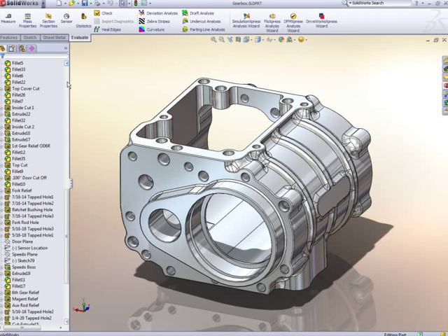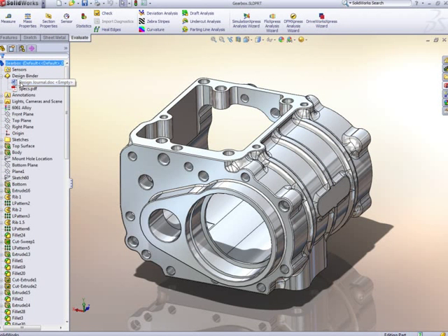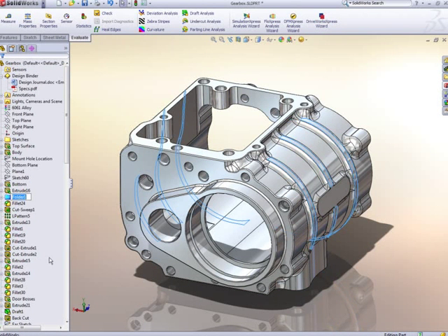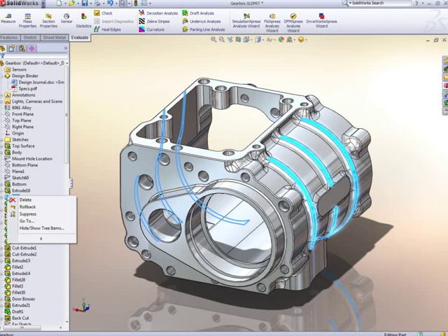Finally, let's see how information is organized in the Feature Manager. Design specs or other documents can be contained within the SOLIDWORKS file, so all relevant information is stored together. Features can be grouped into folders to make the tree easier to read, and then may be suppressed as a group as a fast way of making configurations of parts and assemblies.